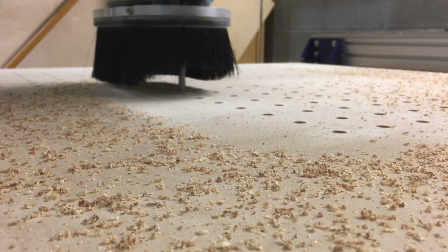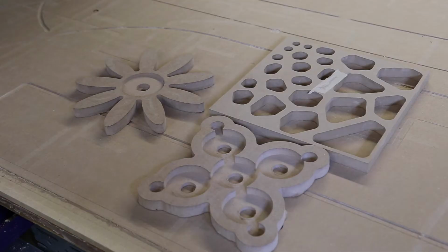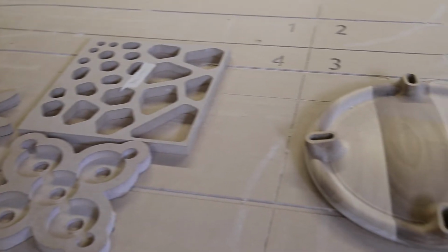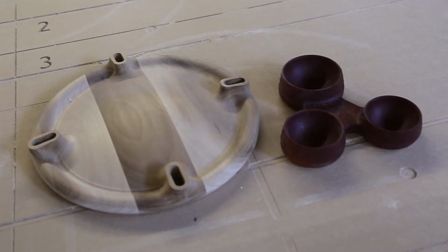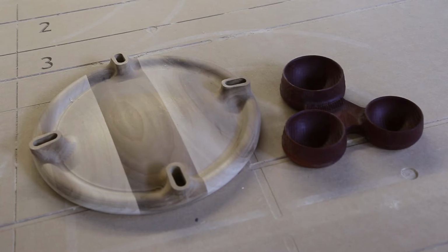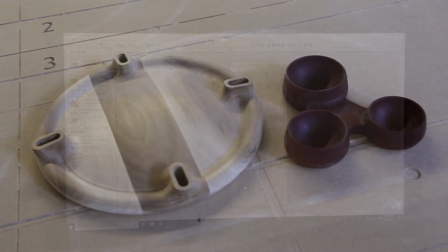In 2D cutting, the Z-axis plunges to a certain depth and stays at that depth while the spindle moves only in the X and Y axes. This is the fastest and most simple form of cutting and normally uses straight end mill router bits. In 3D cutting, the Z, X, and Y axes move simultaneously, allowing complex 3-dimensional forms to be machined. This is a much more complicated type of cutting and requires much longer machining time.